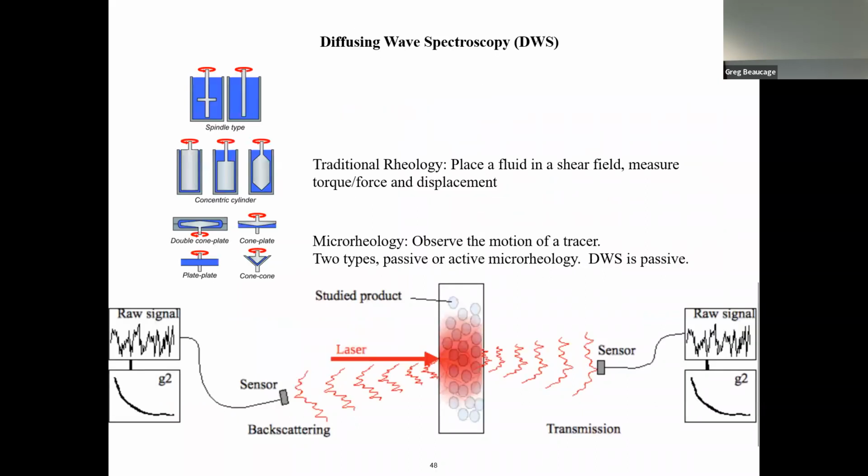He figured out that you could fill the fluid with beads. So this is one type of microrheology: putting a bead in that's magnetic and spinning it, and then watching it move. That's called active microrheology. This is passive microrheology, so it lets the beads move with diffusion, Brownian motion, right? So they're moving around with Brownian motion.